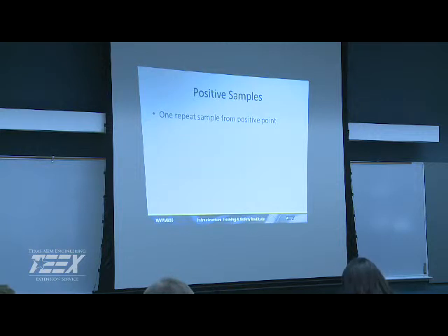Okay. What about source? Are they going to the source and pulling a well? If it's a groundwater system, we just tell them to call us. Yeah. We'll walk through the groundwater rule. Good. That way, if you get a positive, we'll tell you what kind of samples you have to take. Yeah, if you just have one well, it's not bad. You know where to go. But if you have multiple wells, then you've got to figure out which well was running at the time the positive came in, or had been filling that tank, or things like that. So, especially on big systems, you have more work to do when you're going to figure out what your source water potential contamination is. But when in doubt, give a call.